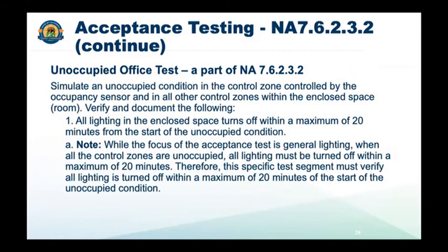And then the last one, unoccupied office test. This is to simulate an unoccupied condition in the entire office space and to verify all lighting in the enclosed space turns off within a maximum of 20 minutes from the start of the unoccupied state.